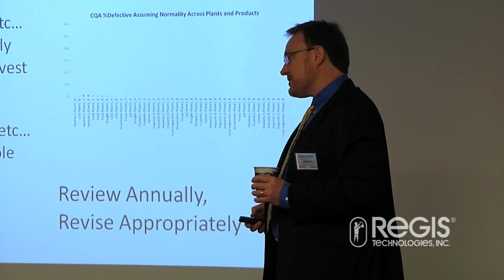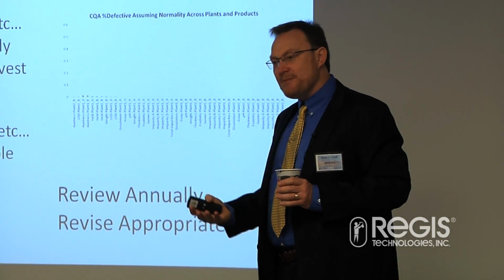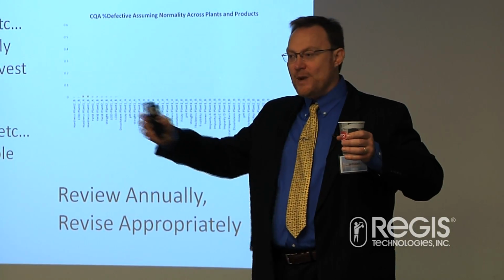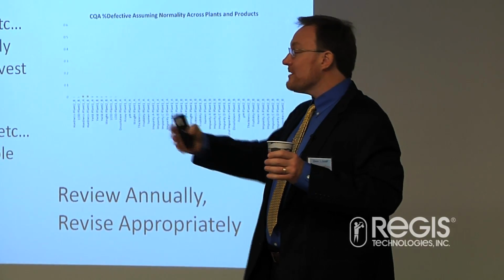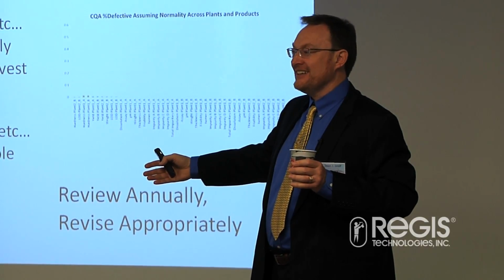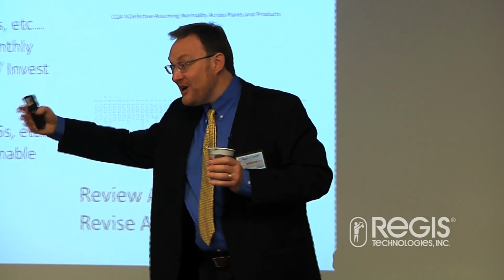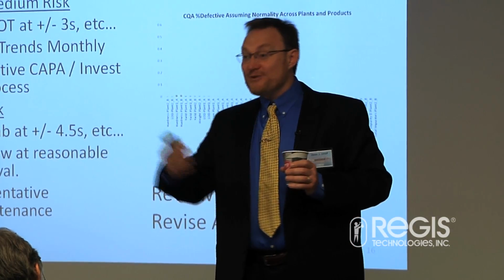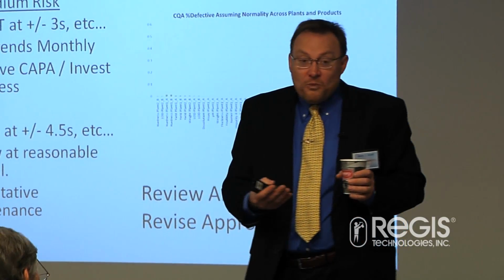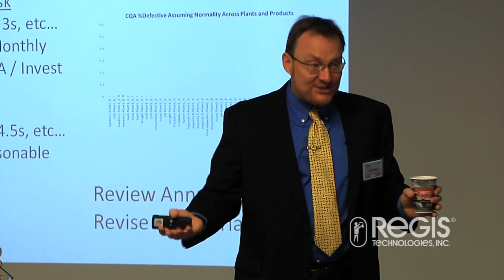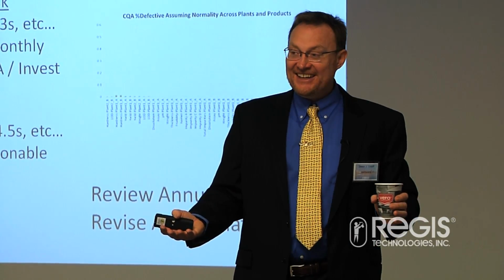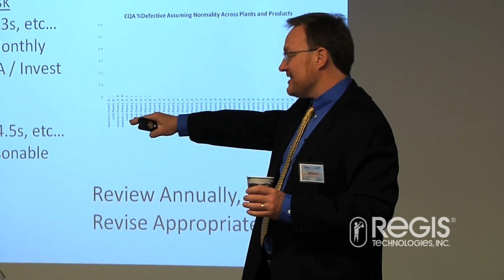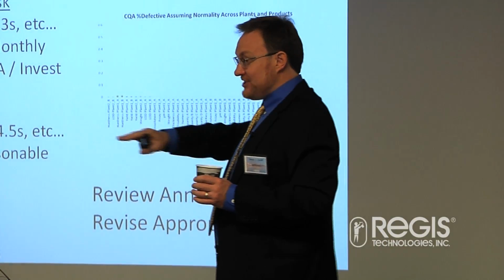And in there, the period with which you revise is based upon the number of lots that you have, the amount of new information you've gathered. So you might go 100 or 200 lots before you revise your process. One of the reasons is we don't want things to change a lot. Yeah? If we have a stable process that's in control, it shouldn't be changing.